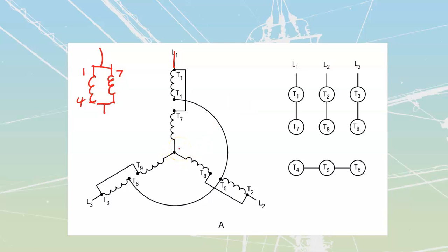These ones over here are going to be the ones where, if you do have a T0, you would want to connect T0 to this line over here as well, because that T0 would just be making this connection from here to here, so that I am going to have absolutely no circulating currents. You can end up with weird circulating currents inside of these ones if you don't have a T0. It's usually not a big deal. In some cases it can be. If you've got just ridiculously bad power factor harmonics, you can sometimes trace them back to low voltage connections on a 9-lead type of motor, particularly the 9-lead Y low voltage.